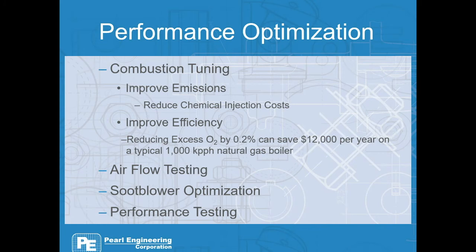If there's any sort of pluggage or damage or leaking on the pitot tubes or airfoils, the conversion from the differential on that device to the airflow that you're controlling your air-to-fuel ratio off of is thrown off. Real-time testing with a handheld calibrated pitot tube can help you to characterize your device so that it is accurate.